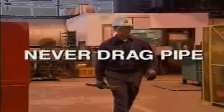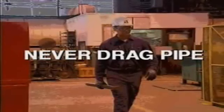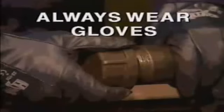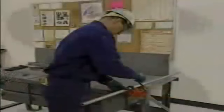Never drag pipes. Dragging a pipe can scratch or dent the outside surface, damage the ends, or contaminate sterilized pipe. Put end caps on pipes during handling and transport to guard against damage and contamination. Wear gloves to protect your hands from rough, sharp edges that could scrape and cut you.